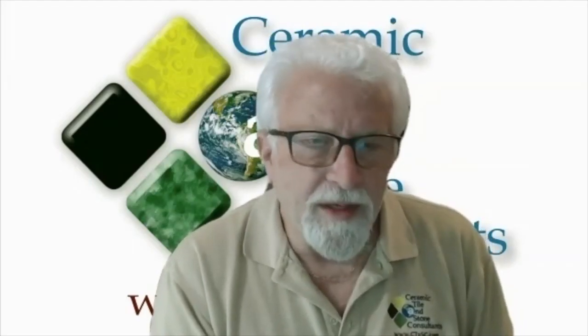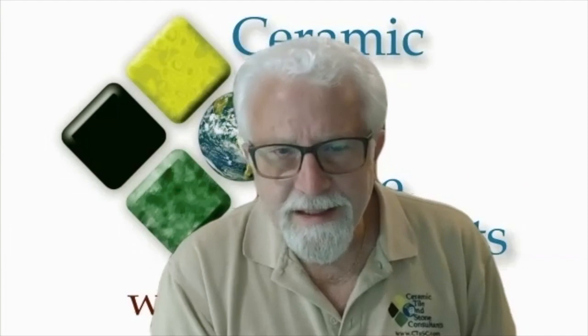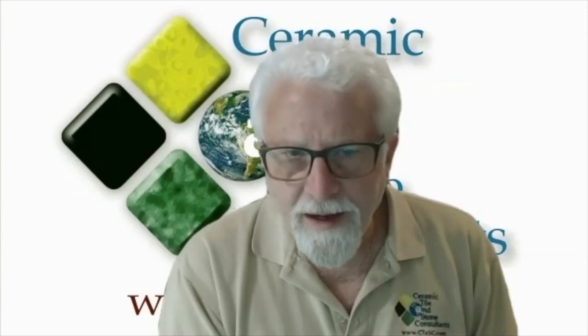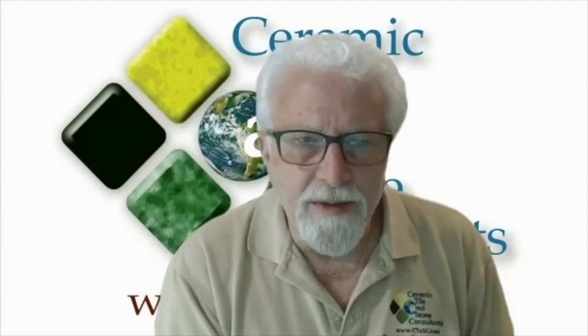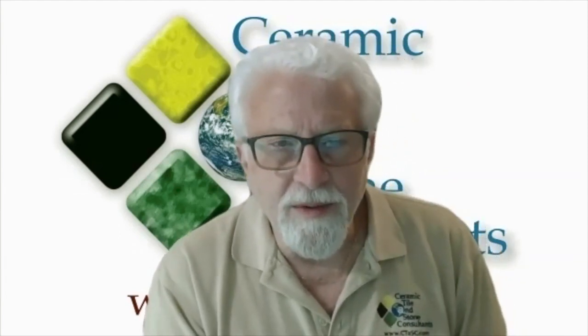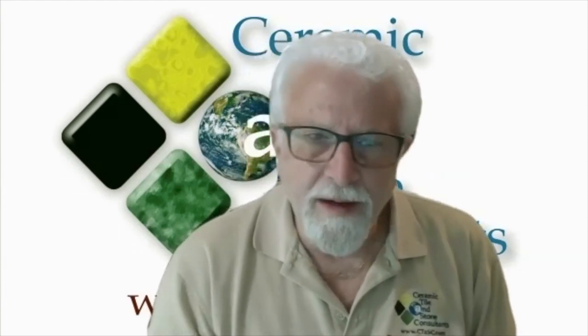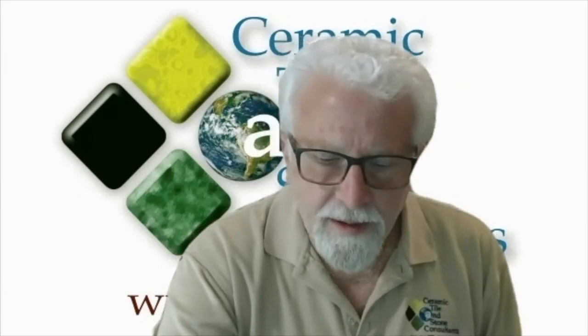You've got to properly install these to make sure they work well. But one of the benefits of this thickness of product, even for commercial applications, is that it's much more resistant to damage. Often, when the tile isn't installed correctly, you have excessive voids under the tile that result in cracked corners and other damage. The thicker material is a little more forgiving, even though we still recommend getting that 95% contact when you're adhering them.